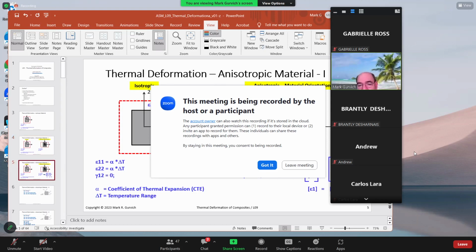As we discussed, matrix definition is extremely convenient for analysis of anisotropic media, including both homogeneous and heterogeneous. So let's rewrite exactly the same set of equations in matrix form. We know already, actually here I need to put 1 here, I forgot, it should be 2. Yeah, thank you. So what we have here is a one-dimensional matrix or vector of strain, epsilon sub 1, consisting again of all those 3 components at the left here.